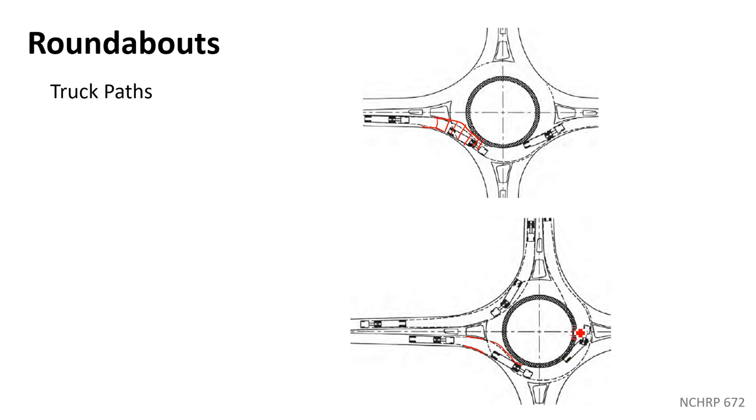And we call this crosshatched area the truck apron. And that is designed exactly for that reason. So that tire is going to continue around. You can see it doesn't get off of that truck apron until about right here. Through that. So that truck apron is specifically designed just for the rear wheels on the semi, on the trailer.